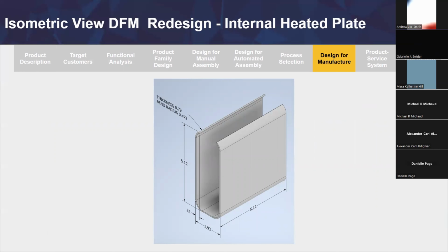Additionally, we increased the wall thickness to 1.1 millimeters, which is within the range for die casting. Here's what the internal heated plates look like after DfM. All the critical dimensions were kept within the specified tolerances.